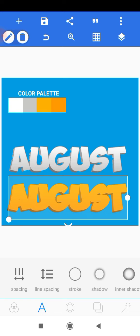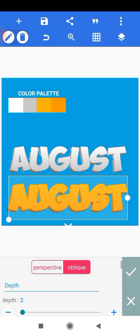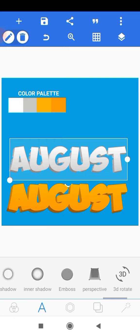So now that I have it there, I want to increase the depth of the text below to 4 pixels. So I'll head on to 3D text and the depth, and I'll increase it to 4, and I'll click OK. So now that I have it there nicely, I want to select this text on top here, and I'll head on to shadow.